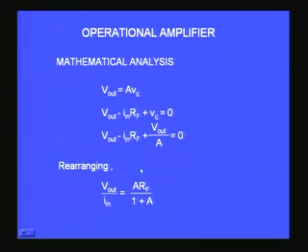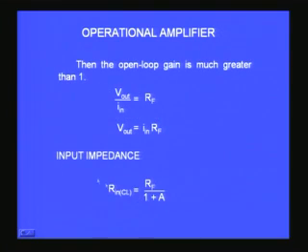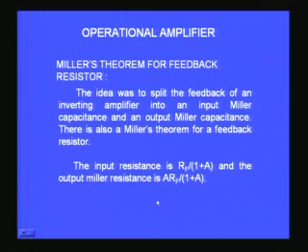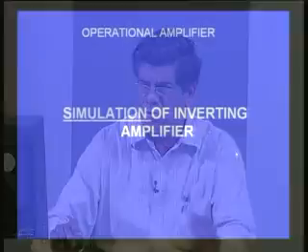If it is a basic current voltage converter, output voltage is equal to I in into Rf except for a negative sign here. So V output is equal to I in into Rf is the output in terms of the input. This I in now, because of the virtual earth, we are generating using a voltage source and a series resistance R1, and therefore you get the corresponding V output is equal to R2 divided by R1 times V in with a negative sign. Now we also know the input impedance of the amplifier will be reduced to Rf divided by 1 plus A, that is what we saw from the Miller's theorem also. That is the effective resistance which will decide. All the other resistances are larger value, therefore the parallel value will always be very close to the smaller value. Miller's theorem helps us to analyze the circuit easily.